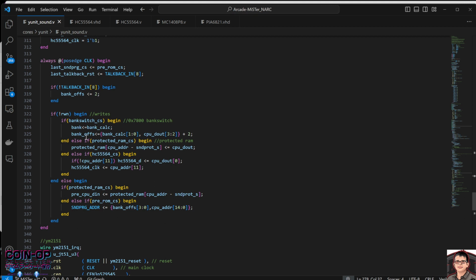Since the audio ROM is big, there are multiple banks, because the addressable area the CPU can address in the ROM is small compared to the whole size. So the ROM is divided into different banks, and before the CPU makes a request to read ROM, it switches the bank.